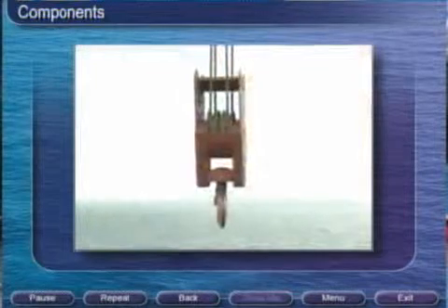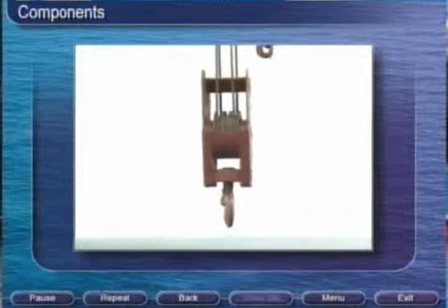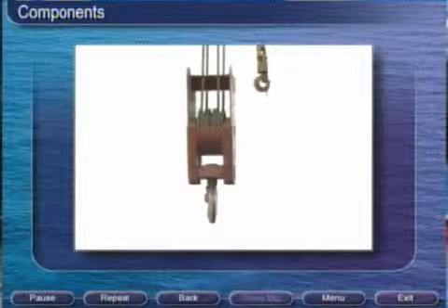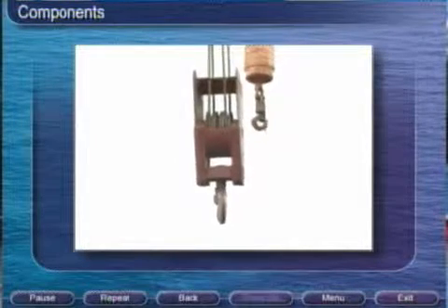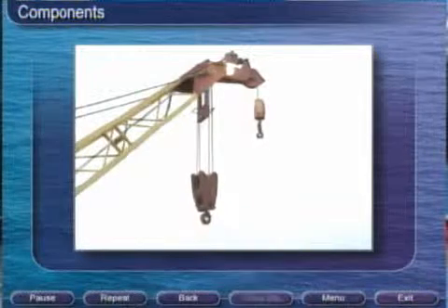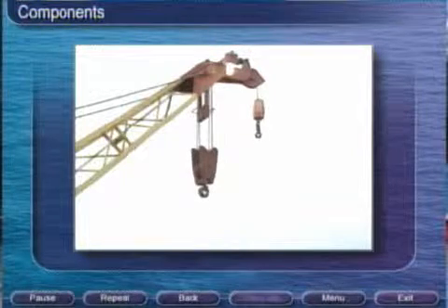The main hoist is used to lift heavier loads. This hoist uses multiple parts of line and moves much slower than the auxiliary hoist. Check with your crane's load chart to verify the capacity of this hoist, which will vary depending on the parts of line used.